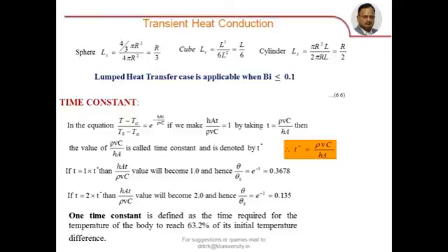Yes. For example, take a copper wire, electrical copper wire, maybe 20 gauge or 30 gauge. The diameter is very small, and when current is made to pass through, its temperature rises. Because of its thin, very small diameter, the temperature at the center and at any position, at any radius within that wire remains the same, negligibly small.